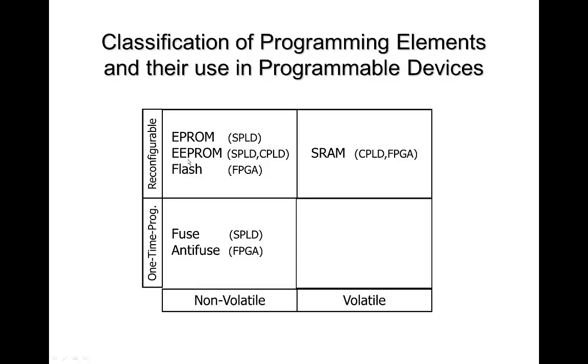I guess one word about the EPROMs: flash or EPROMs are the oldest technology. What they actually do is there's a floating gate on the transistor, and we use tunneling to put some charge on the floating gate. Erasing that charge on the floating gate makes the source and the drain connected, just like a regular transistor. Now, to erase it in an EPROM, you actually had to bathe the chip in UV light for maybe 30 minutes or so. So we'd put a quartz window on top of the chip and bombard it with UV light, which would eventually knock off all those electrons on those floating gates.